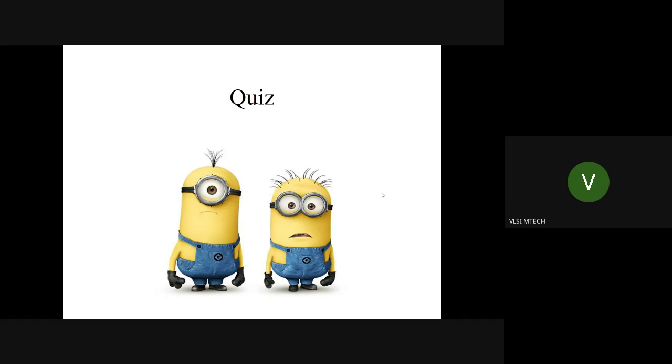Here's the interesting thing. Earlier, when we were talking about the 90 nanometer node, 65 nanometer node, the node number in a way correlated with the minimum feature length, which was also in most cases the gate length. However, now, because of the whole marketing thing, people have been naming their new technologies using a lower node number, but that does not imply any connection to the gate length anymore. So even Intel's latest devices are larger than 10-15 nanometer gate length.